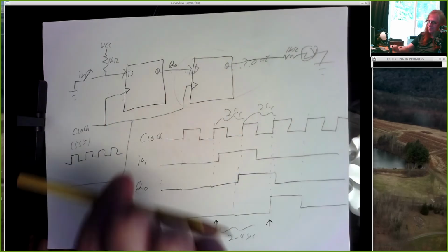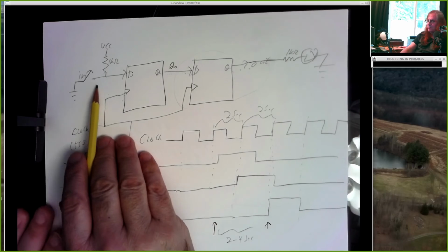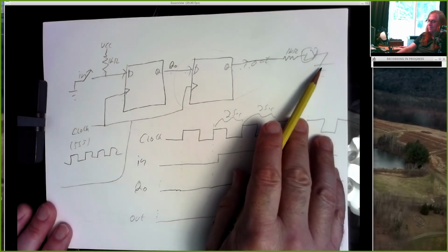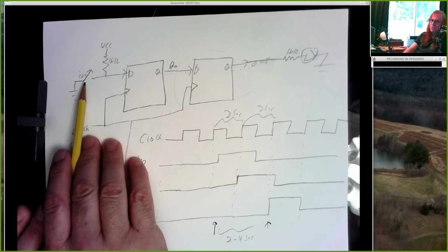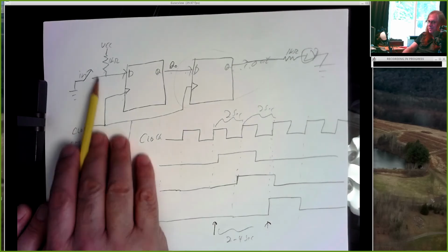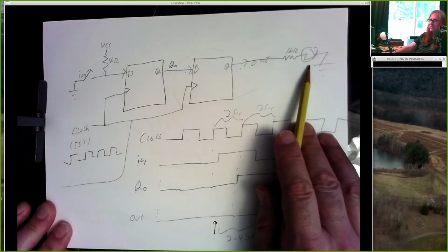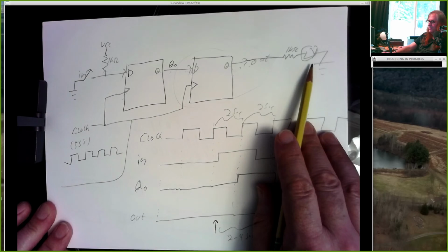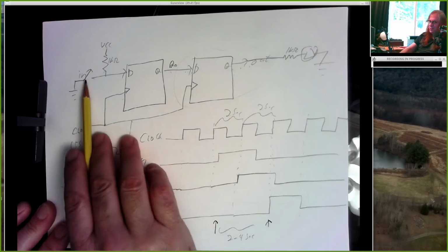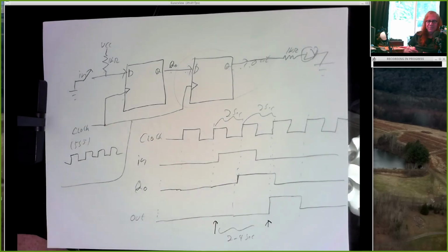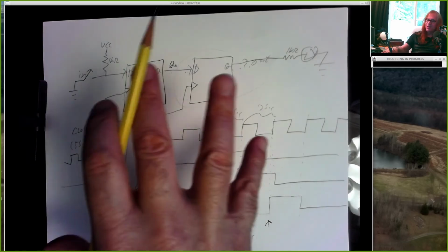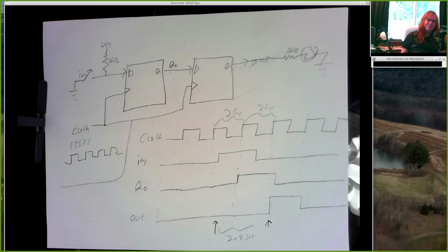Well, pushing the button will actually make the light turn off, because when the button's open, it's a logic 1. So push the button and 2 to 4 seconds later the light goes off. And then release the button and 2 to 4 seconds later the light turns on. Right? When you get this right, it's really, really obvious from running that simple experiment.